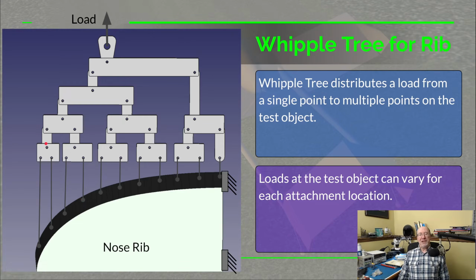But then it attaches to another load spreader, so I have to calculate those hole positions. Now these will be bolt holes so that this can swing. And then of course the level 3 and then level 4 load spreader. So what we need to calculate is the distance between these holes and the position of the next load up